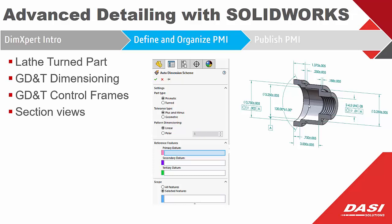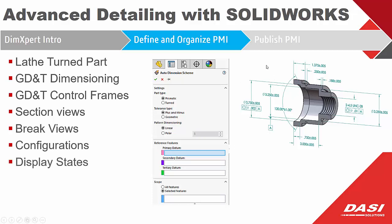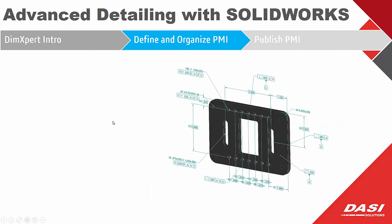We need to clearly illustrate internal features versus external features. So for that, we can use a section view. I want to show you how MBD supports section views, and also model break views when views or assemblies get very large. Sometimes we want to create break views, and MBD has a good way to support that. We also support configurations. We might have a long version or a short version of this part. We might have various display states for our work instructions where we want to show masking or plating should be specified, so I can use different appearances and colors for plating callouts. Those are just some of the additional things that we can support with MBD.